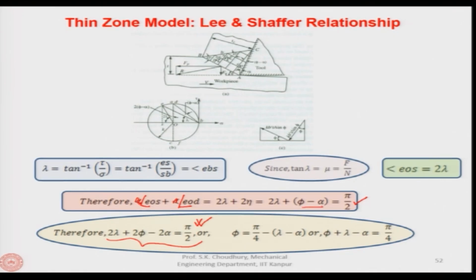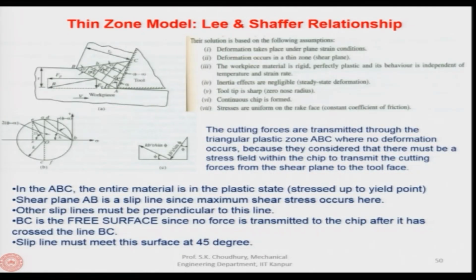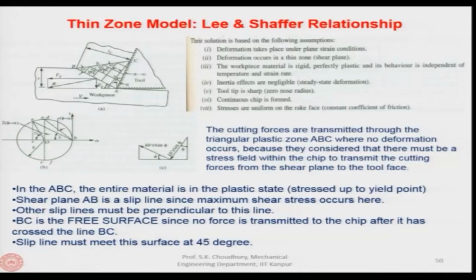I once again would like to repeat that what is happening here is that this stress field is made. In this stress field, these are all the slip lines where the maximum deformation occurs. Each of these lines is given a name, for example D, E, A, B, C, F and so on. Here they are all maximally deformed, and they make an angle of 45 degrees with the free surface. Therefore, in the Mohr circle it will be twice that, which is 90 degrees.